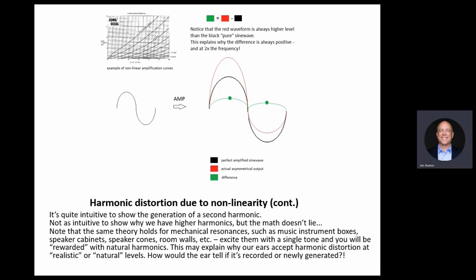So if we put a small signal in, and let's say this is a 2x gain, this is the signal we expect. We expect the black signal there. Instead, because at the higher voltages it got more gain, we get the red thing.